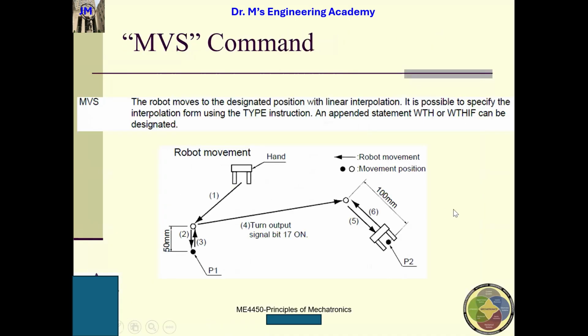So MVS, and you can see the MVS very clearly. This just moves the hand in a straight line. So be very, very careful, okay? You can use MVS only if you are sure that between this location and the destination location there are no obstacles, no people or other things, because you don't want to damage them, right? I'm kidding. Be very careful.